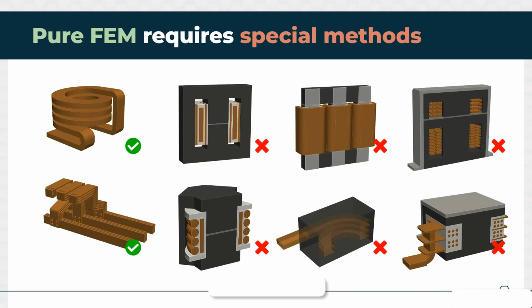And it's very important to understand that the FEM, the finite element method, and AV formulation in the pure form is not very useful, and there will be a very limited number of problems that you will be able to solve with a FEM solver which you write yourself. The reason is that we need to put a lot of different numerical methods on top of this pure FEM discretization in order to make it useful for solving magnetic problems.